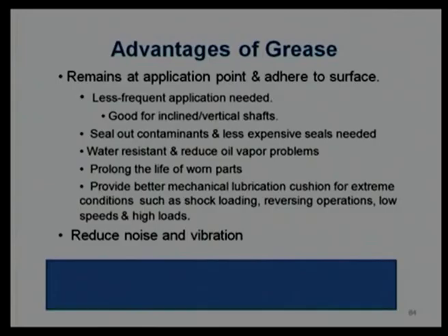Now, this slide shows some advantages of grease compared to solid lubricants as well as liquid lubricants. Compared to solid lubricant, one of the major advantages is that it remains in contact with the surface and can be replaced easily. With a liquid lubricant we require frequent supply of the lubricant. That is why we say that less frequent application is needed when we compare with a liquid lubricant.